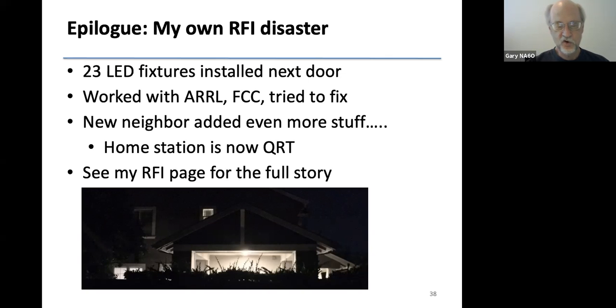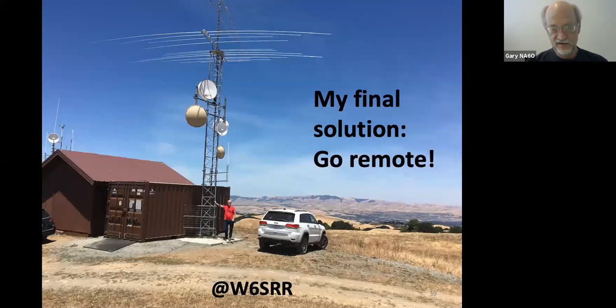So I kind of abandoned the home station, and I have a remote station up on top of a hill, which is absolutely fantastic, thanks to a partner of mine I work with. But even this has other noise. You can see these other dishes there. That's commercial microwave gear. And there's other power supplies. There's an adjacent little tower you can see way off to the left. There's all kinds of noisemakers up there. And I estimate I have over $1,000 in ferrite just at this station trying to mitigate these other noise sources. I can't get rid of them all. They're in all bands. So, no place is perfect. I do everything I can to fix it though.